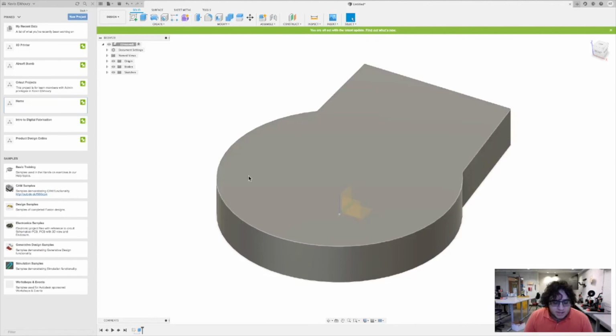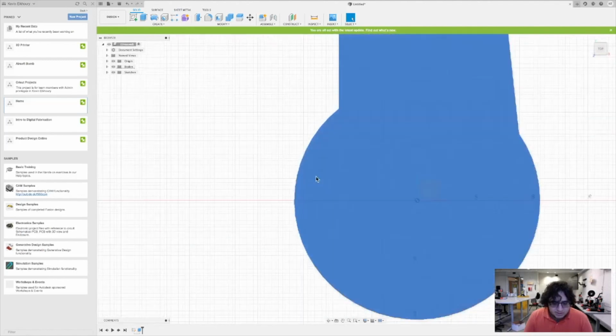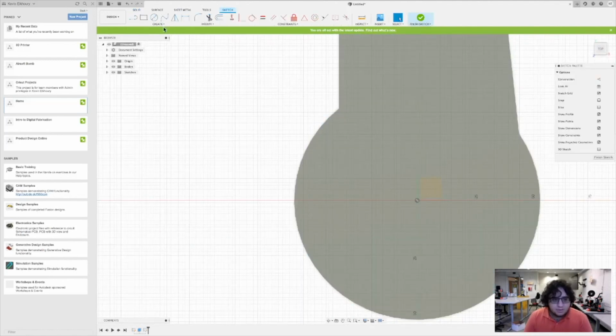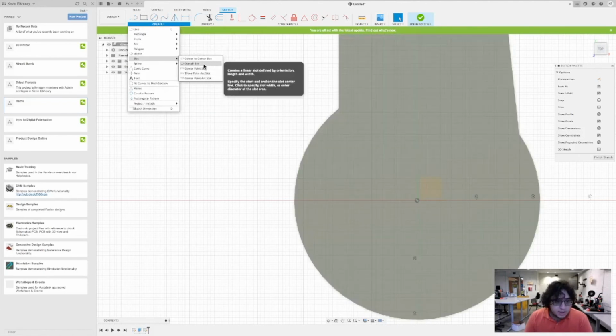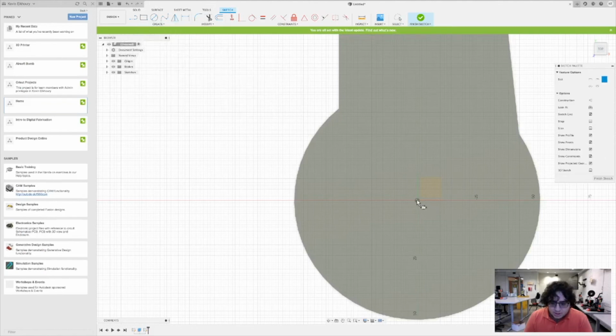Well, imagine now that we want to add a shape on top of this shape we just made. We'd be able to right-click this plane, just as we right-clicked the plane at the beginning, and say that we want to make a sketch on this plane. All right. Now I can create for myself an ellipse, let's say. We're going to make it an overall slot ellipse. Define it by the origin. Once again, its only definition is the origin, and it must intersect at that midpoint there. However, past that, I can move it how I please.